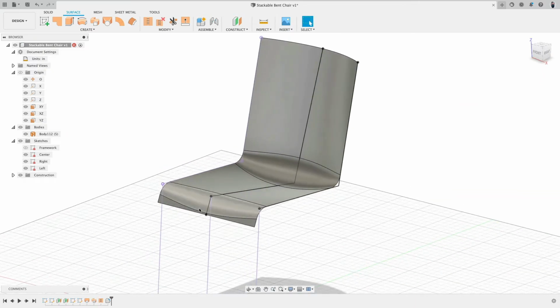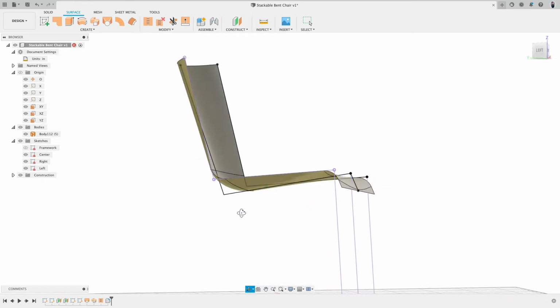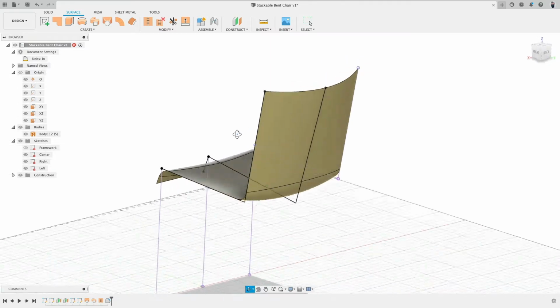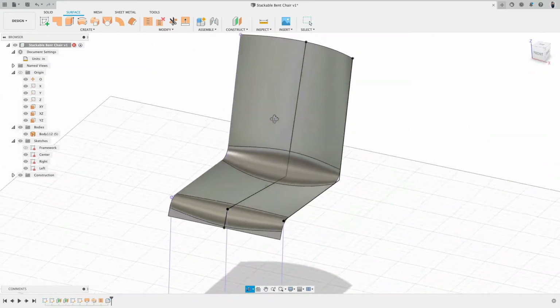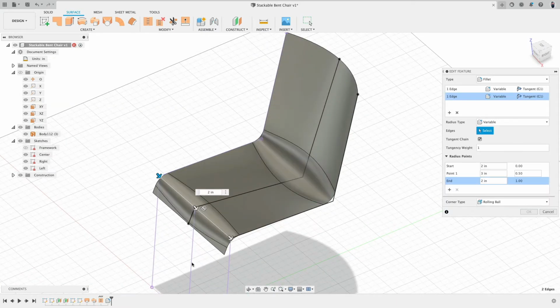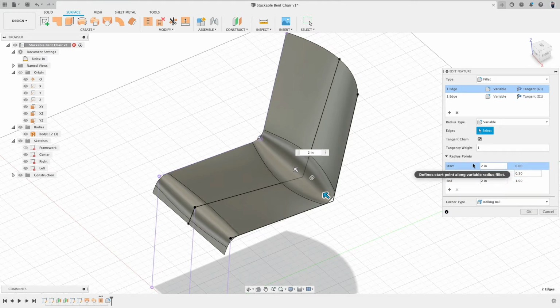We get kind of very thin here at the end. But you notice how, because of the variable fillet, this surface actually starts to arc a little bit. Here definitely this looks good. This might actually be a little bit too childish, so maybe we just go to 2.5, not to make it as big, but maybe have a little subtle something changing there. And then here, instead of 2, we change those to 3.